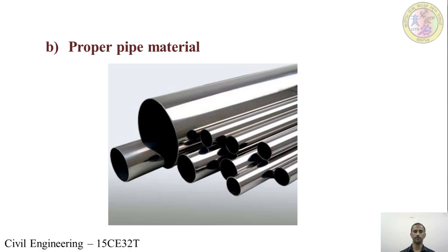It is also to be noted that any impurities present in the iron steel materials while manufacturing pipe may lead to increase in corrosion. These impurities may be tin, lead, copper, etc. Care should be taken to remove these impurities so that the manufactured pipe material has best resistance against corrosion.